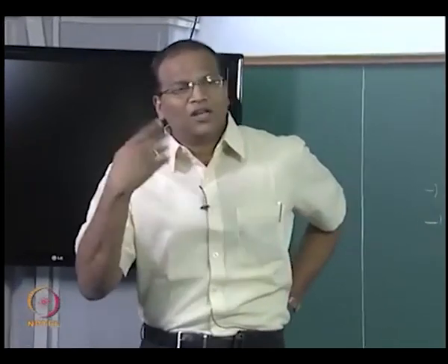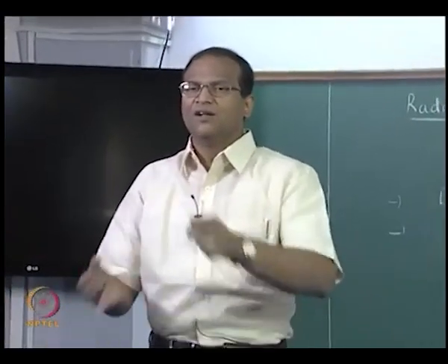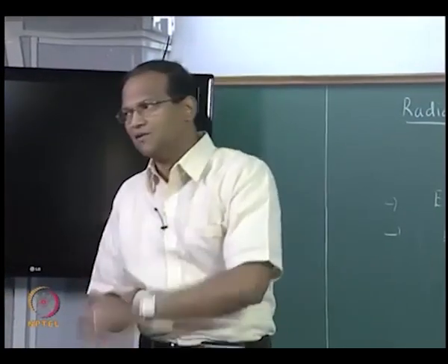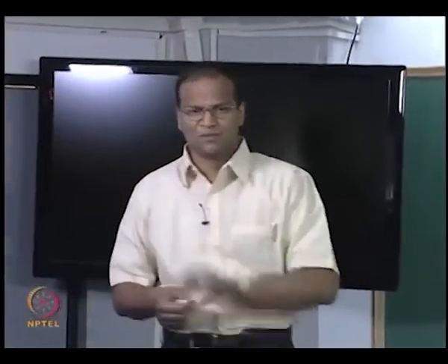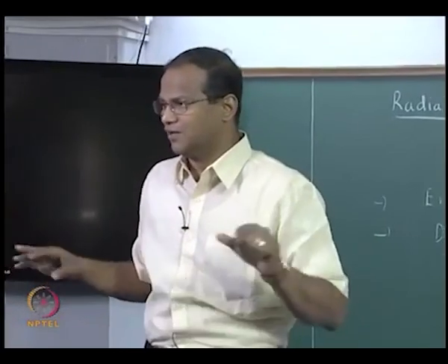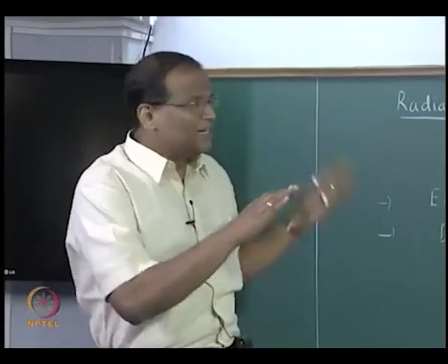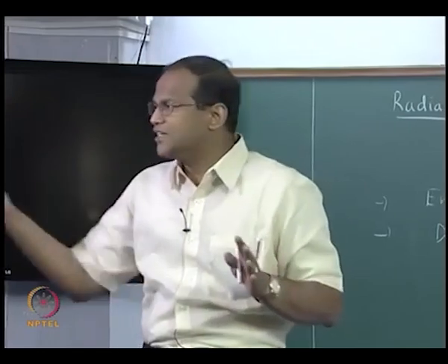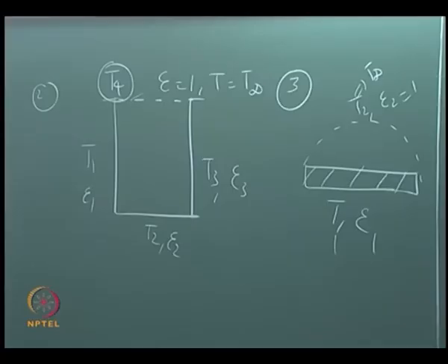But with the information you already have, that is the last 2 months looking at the radiation physics, looking at the Planck's distribution, then the integral version is sigma T to the power of 4, then looking at all the emissivities, absorptivities, transmissivities as a function of angle, as a function of wavelength and all that, that knowledge is not enough, because that is all fine if you want to calculate radiation from one surface, but now you are looking at radiation from an enclosure.